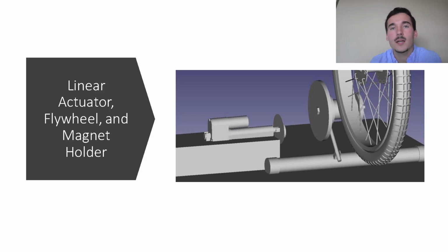So our flywheel, we're going to cut it out of a 1/2 inch thick aluminum sheet, and the diameter of the circle is going to be 8 inches. Then we're just going to replace the steel flywheel that is already on the Uniski bike stand with our new cut aluminum flywheel, and that'll just be one bolt. We're going to have to unbolt it, and then we'll have to bolt it right back in.